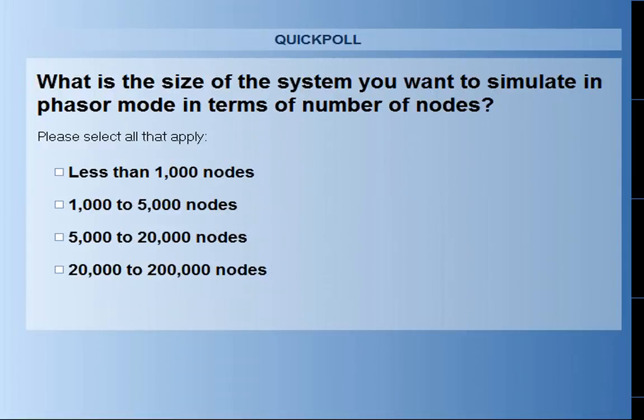This slide shows a quick overview of the eastern interconnection, using real PMU data. You can see the angle difference across different areas, indicating a high level of system stress. And next, this shows the mode meter application monitoring ambient oscillations, which gives you the estimation of modal frequency, damping, and energy level, along with other visualizations for the associated information.